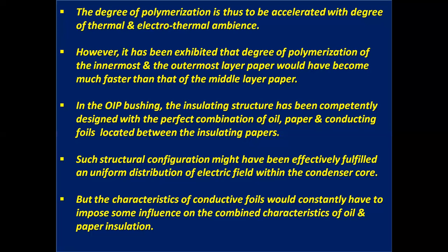Such structural configuration effectively fulfills a uniform distribution of electric field within the condenser core. But the characteristics of conductive foils would constantly impose some influence on the combined characteristics of oil and paper insulation.